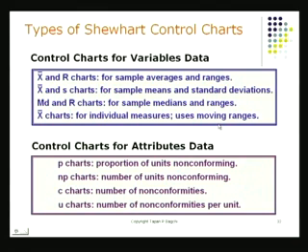Now that you have understood what control charts are, you've looked at an X-bar chart and an R chart. I'm going to be showing you some more of those. The other charts are all very similar. The spirit is the same. Try to distinguish between exceptional variation and natural variation. The moment there is exceptional variation, this is when you'd like to take some action. And leave the process alone if the variations are natural.